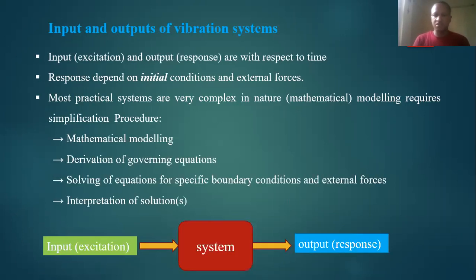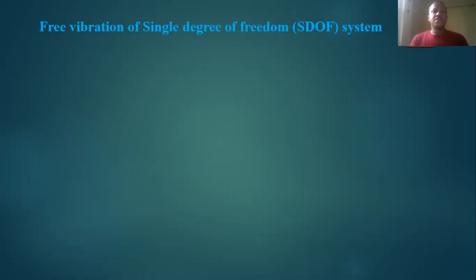Actually, that's why most of the time vibration analysis can be done using the Laplace transform function. So we can give input here, the system is here, output here, and we can make a feedback loop here. Then we can make a control system and solve it in the Laplace transform equation. Free vibration of single degree of freedom system.